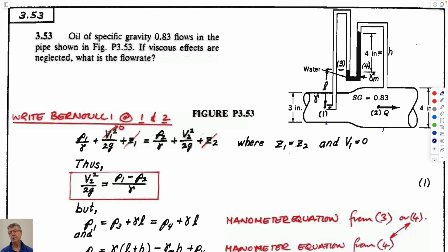You have a velocity upstream, you have a velocity downstream. You can write Bernoulli along that line between those 2 points, at points 1 and 2. You can look at what the conditions would be here. This is stagnating, so velocity 1 is equal to 0. It's hitting the pitot tube. The pressure is not equal to 0, so you don't know what this is. The pressure 2 is not equal to 0, so we want to know what this is. And the velocity 2 is probably not equal to 0 either. It has some velocity.